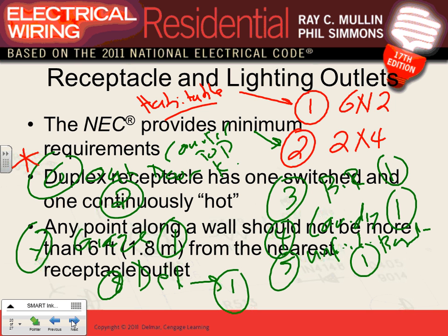So then, does it end up getting charged to a particular apartment? When we get into our apartment, we're going to have a common panel or house panel, they call it. That common panel is going to feed all the common lights in the hallways, all the common receptacles, including the outside receptacles, the swimming pool. I think the laundry, we put the laundry as pay laundry, charged to the common. So these are where you're going to pick what's common and what's not common.